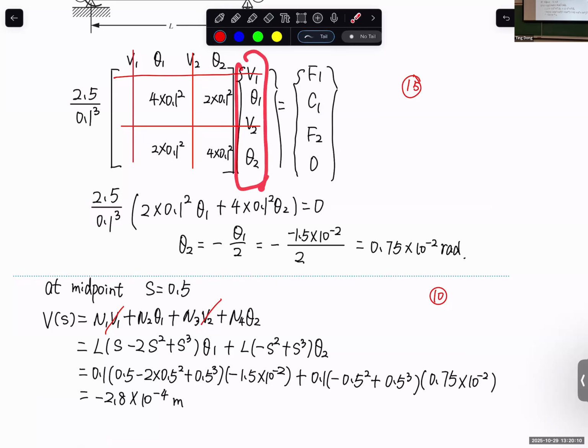Yeah, I think I did that wrong, but I didn't set it up in matrix form. For solving unknown degrees of freedom, the only way is KQ equal to F. There's no different way. FEA is all about KQ equal to F. What different method can you use? I used two equations, two unknowns, but I didn't set it up in matrix form. I just used this equation and then this equation.